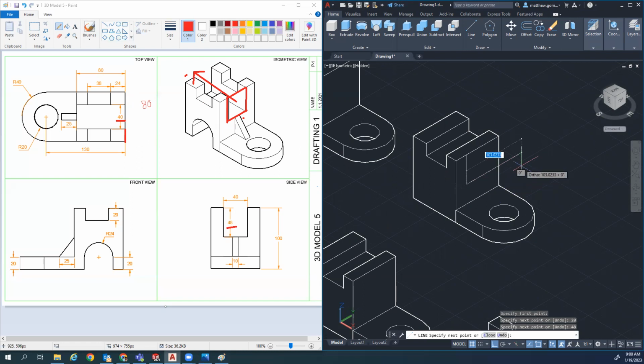And then I'm going across 40, as it says in that picture. And then I'm going back up again 48. You don't have to draw the line going all the way back, because you've got the box. That's all we wanted was the box. Once you have the box, same thing we did on the other side. We press pull, click on the inner face like that, and we cut that section away as well.